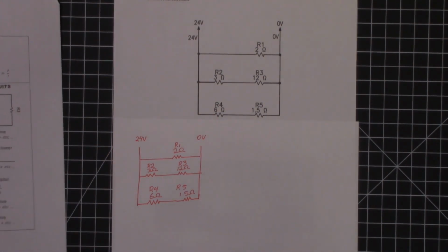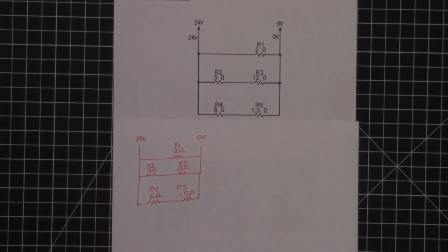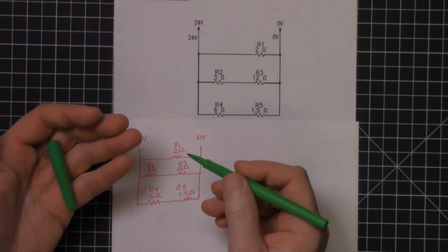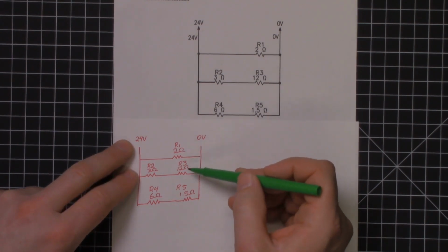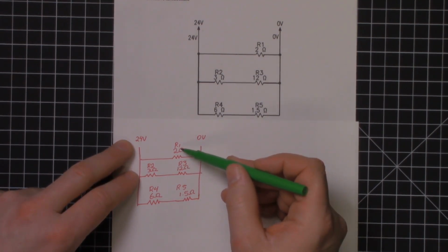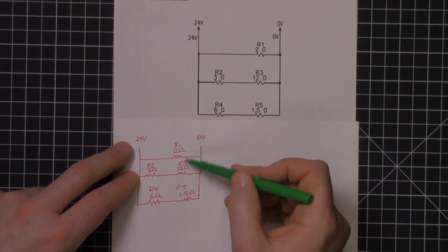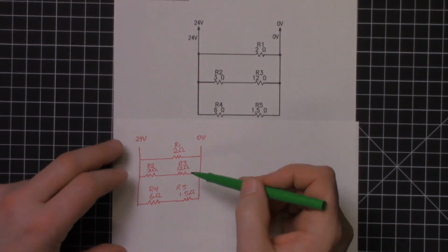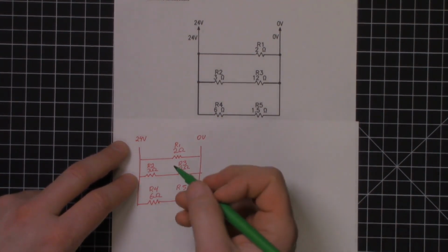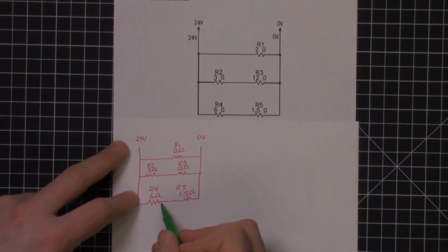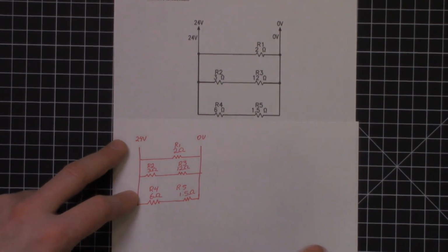The reason for redrawing this is that we need to find out what is in what I would call simple series or simple parallel. So we're going to take a look at these and say, okay, what is just straight up simple series or simple parallel? When I look at this, resistor 1 and resistor 3 kind of look like they're in parallel, but it's not simple parallel because you've got another element over here, right? So what I'm getting at is that resistors 4 and 5 are absolutely in series, right?